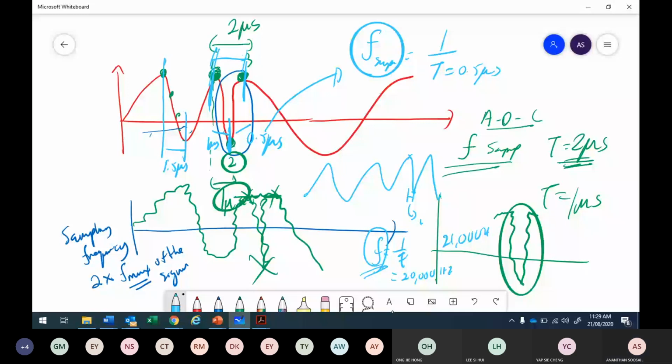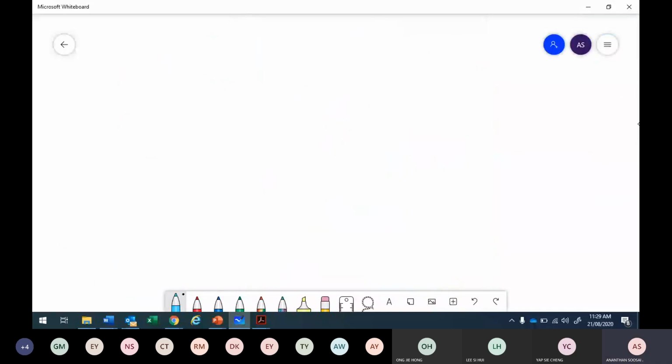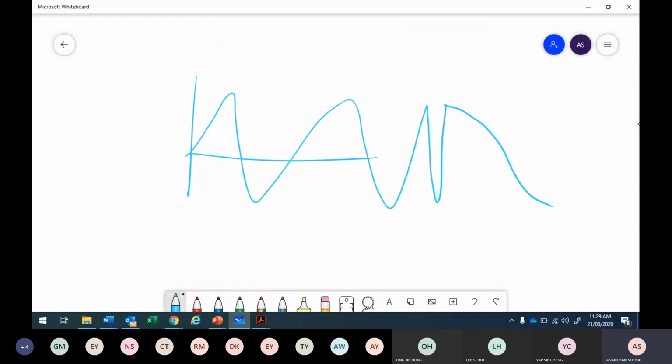So in exam, remember, if they ask you to suggest a maximum frequency and they show a signal, you search for a crest and trough, the shortest time interval between the crest and trough, and the frequency is 1 over that time. Whatever value you get, you put it slightly more than this, so the crest and the trough are recoverable when they trace the digital shape.